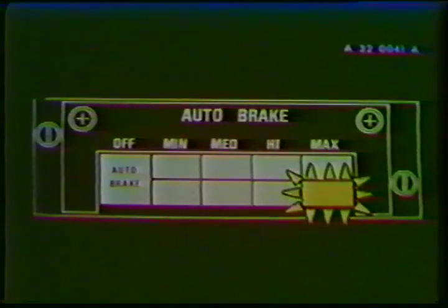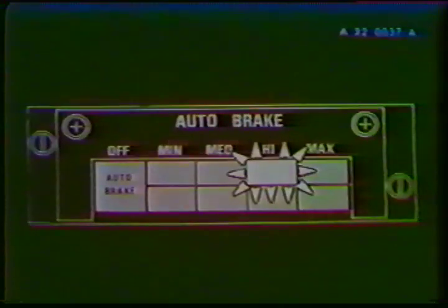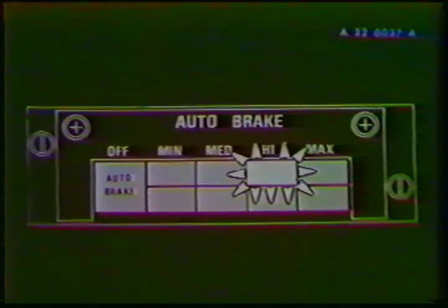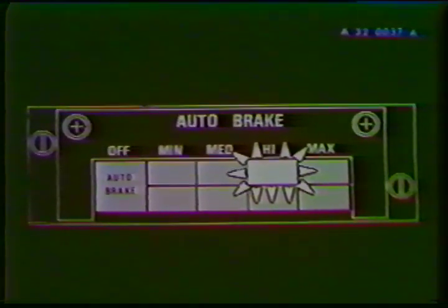When cleared for takeoff, the system is to be selected to the maximum mode and the white portion of the push button should illuminate. In case of an aborted takeoff, maximum braking is automatically applied when the ground spoilers are extended. Immediately, the green light will come on when braking action starts. During approach, a mode will be engaged considering landing weight and runway length. As soon as the mode is selected, the white portion of the push button is illuminated.